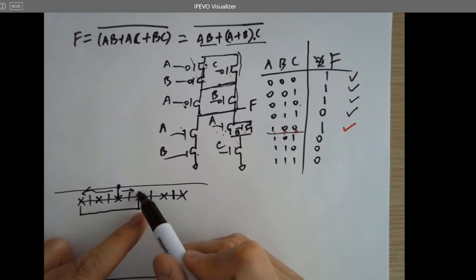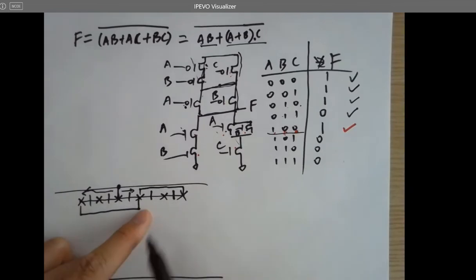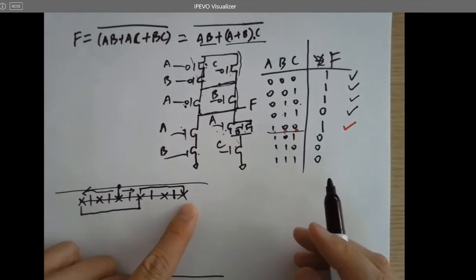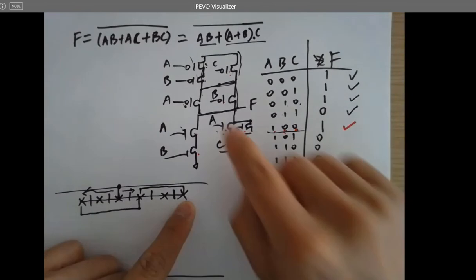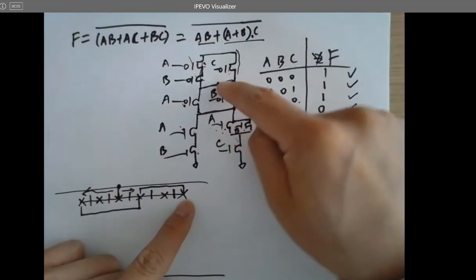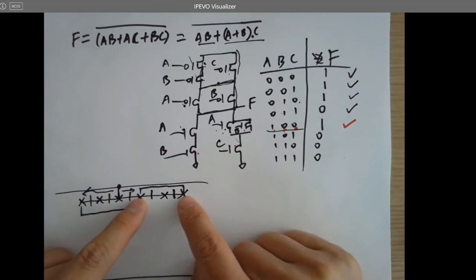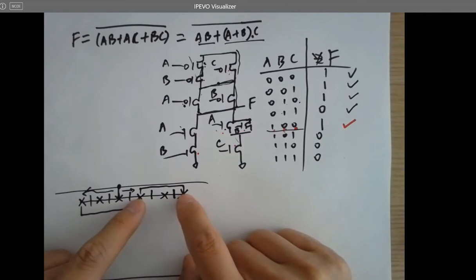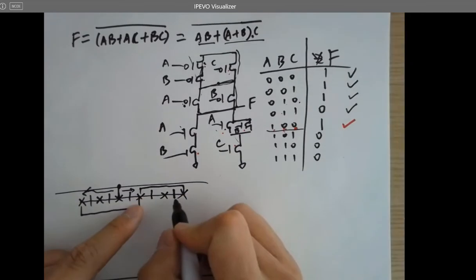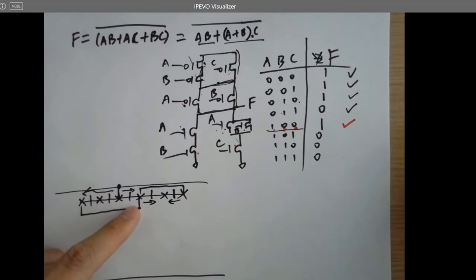So what I'm going to do, I will just make the connection from the top. Connect to here. So it's like from this node, right? This node is connecting the sources of these 2 PMOSes, and so the current is going to flow to here and to here because this is one node.